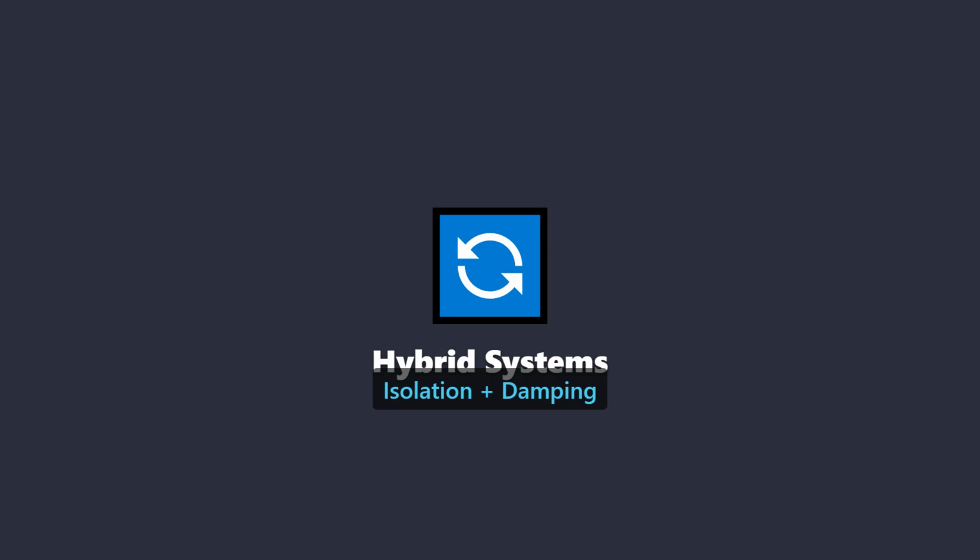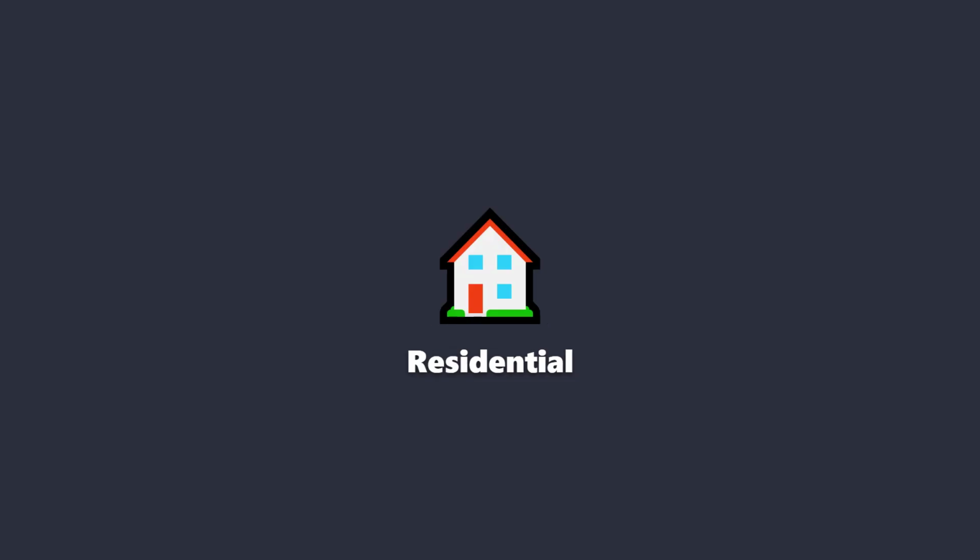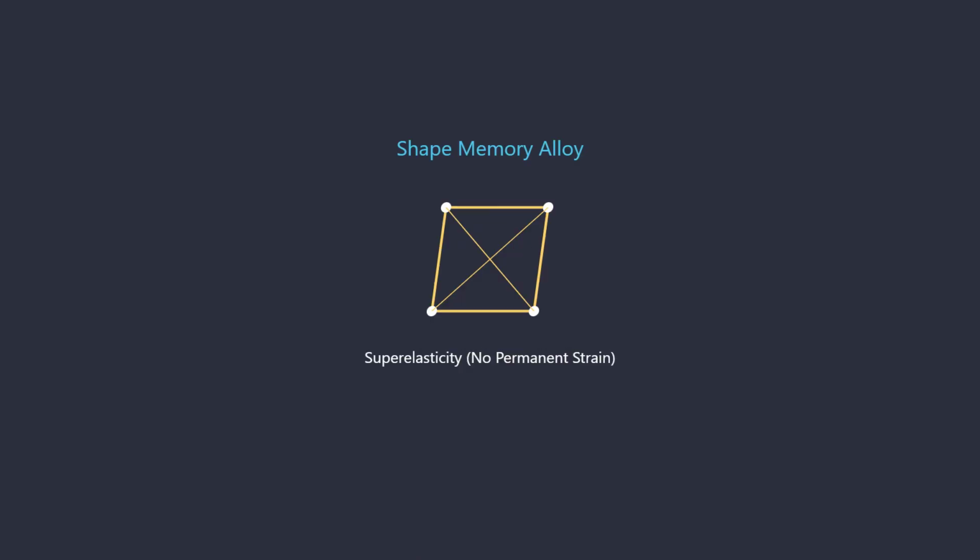and energy dissipation capacity. Although historically cost-prohibitive, base isolation is becoming increasingly viable for multi-story residential buildings located in high seismicity zones. For single-family homes, smaller modular dampers are being developed specifically to mitigate non-structural damage, which often accounts for the majority of repair costs.